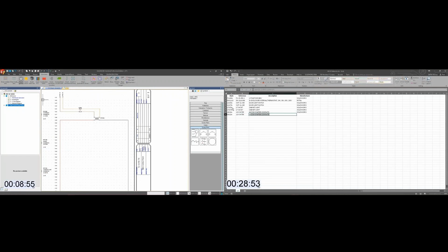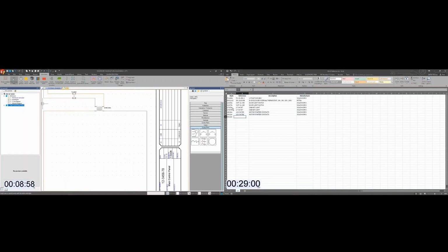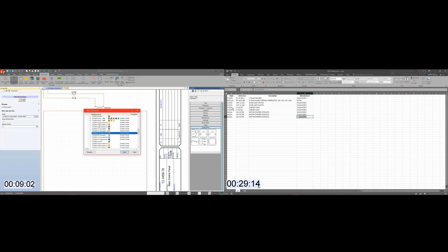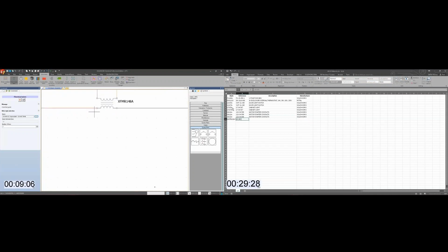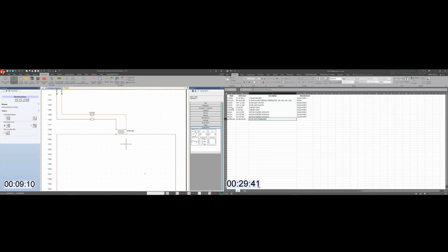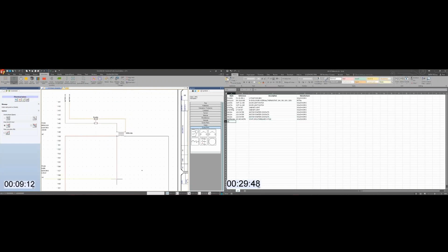Checking back in, we're going into 9 minutes in SolidWorks Electrical, getting ready to build out that little circuit for the cabinet lights and door switches. Here I'm just putting in intelligence. It knows snap points. I'm using ortho to help me ensure that I'm drawing in the appropriate direction. So you have all the features you're used to as far as snap, object snap, ortho mode, grid, etc.